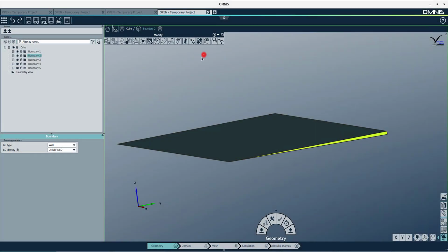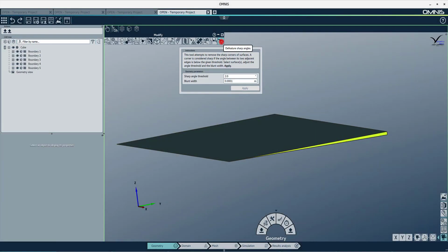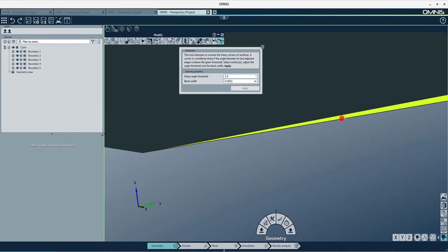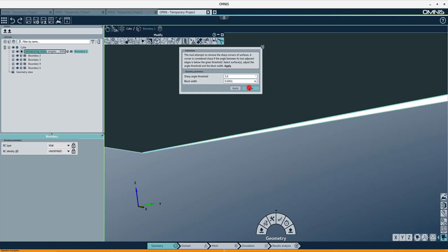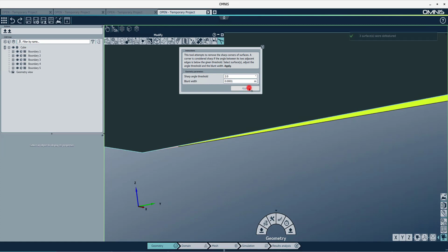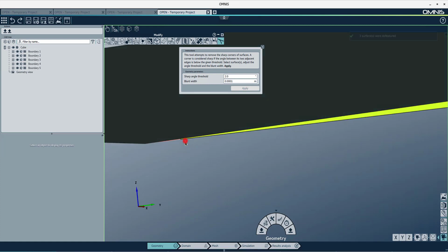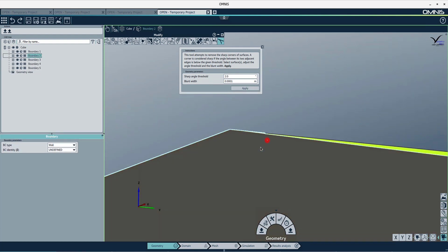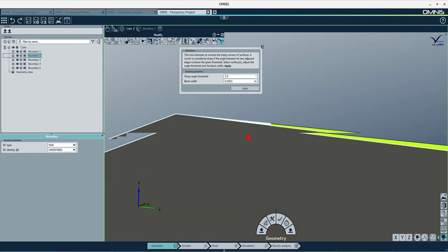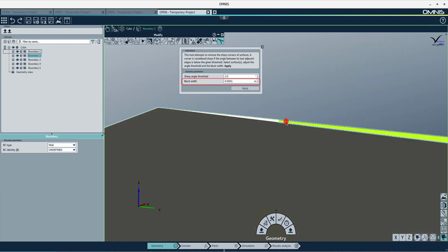Finally, the Feature Sharp Angles tool detects and removes the very sharp angles in the geometry that would produce bad quality cells. This tool should be used with care on a surface-per-surface basis to avoid undesired defeaturing. This algorithm cannot be executed on multiple bodies, so no defeaturing will be applied between bodies. In addition, the geometry must be conformal near the corners to detect. The blunt width parameter defines where the algorithm will apply the cut.